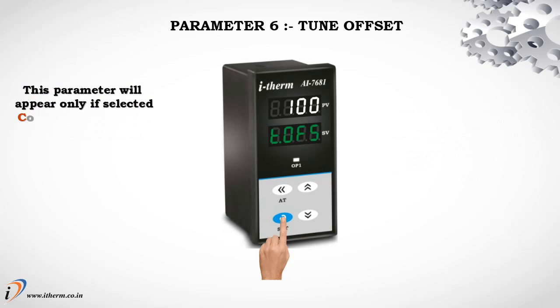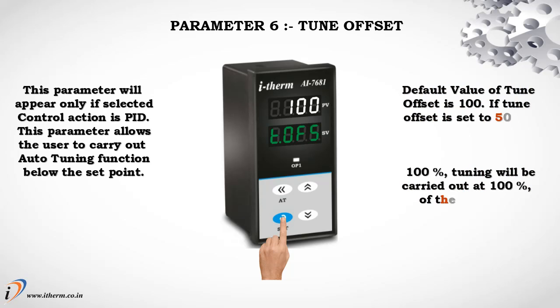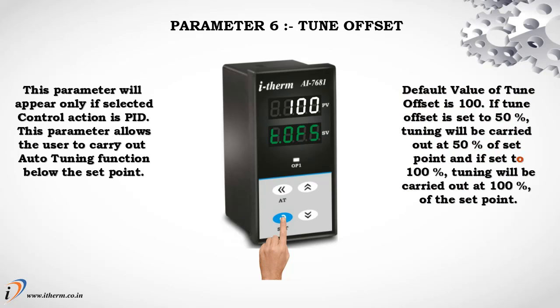Parameter 6, tune offset. This parameter will appear only if selected control action is PID. This parameter allows the user to carry out auto-tuning function below the set point. Default value of tune offset is 100. If tune offset is set to 50%, tuning will be carried out at 50% of set point, and if set to 100%, tuning will be carried out at 100% of the set point.